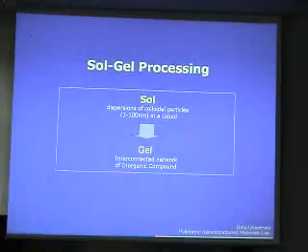On the other hand, the sol-gel processing method is pretty simple. We put everything together in this batch and then let it evaporate to get the interconnected network of the inorganic material. And the shape control and morphology control of this material is easier than with the hydrothermal precipitation method, and we can create monoliths, fibers, or any kind of bulk material using this sol-gel process method.